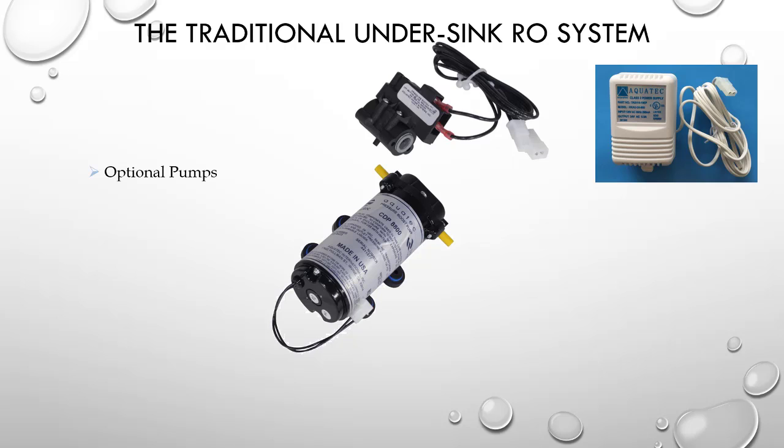Add the pressure loss in a home during regular household use, such as flushing of toilets, laundry, or other water usage points. Plus, if the home had low pressure to begin with, all this would add up to an RO possibly or potentially performing poorly. This is why pumps are very helpful to traditional RO systems with air captive storage tanks.